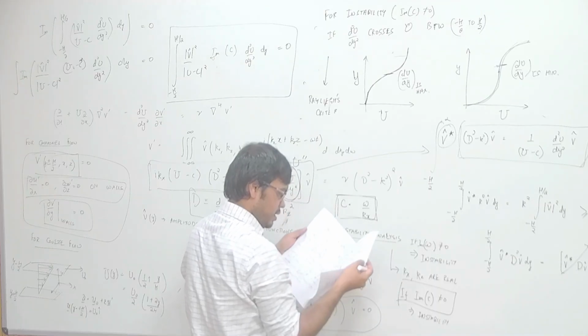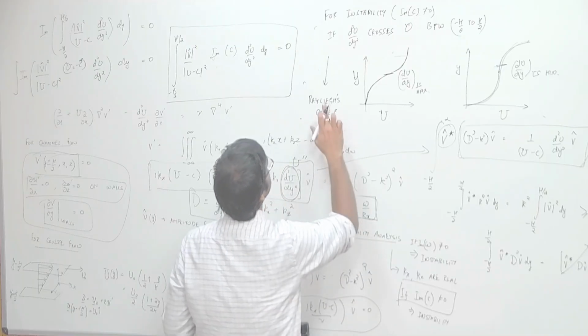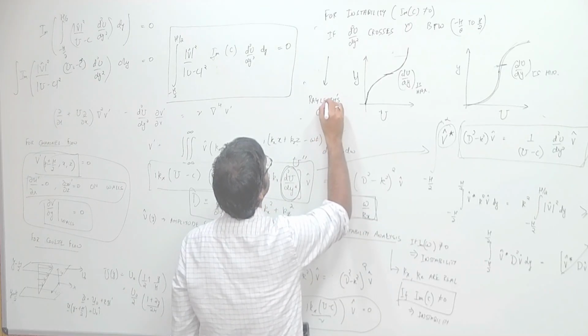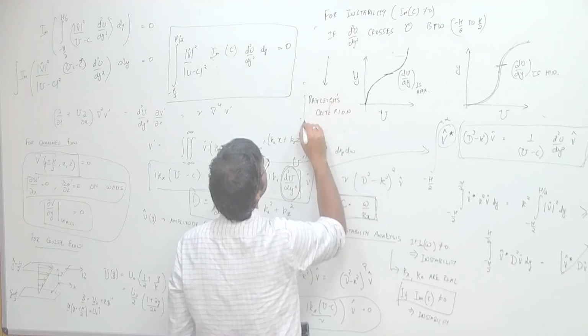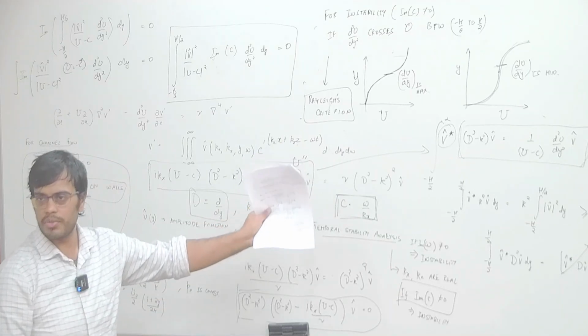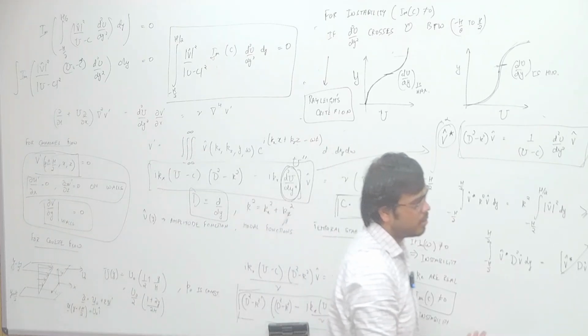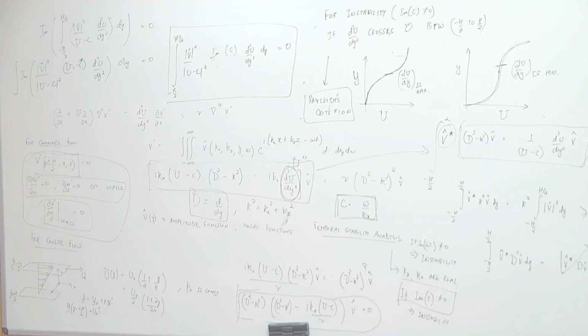Which one is it, IE or EI? It's EI, I think. Yes, this is called Rayleigh's criterion, and it is not a sufficient condition, but it is a necessary condition for your inviscid perturbations to be unstable.